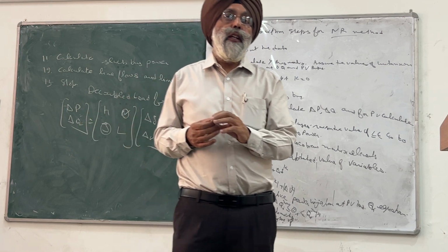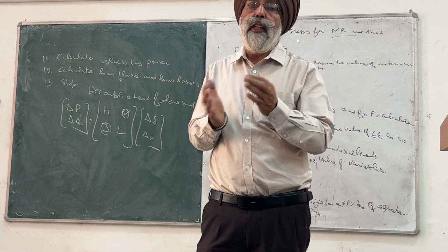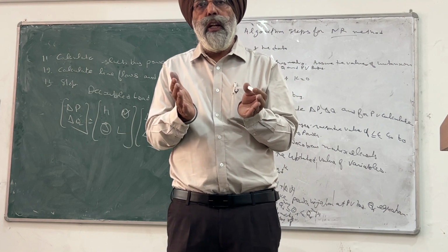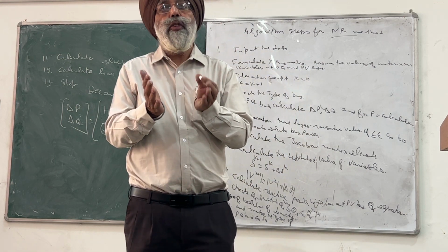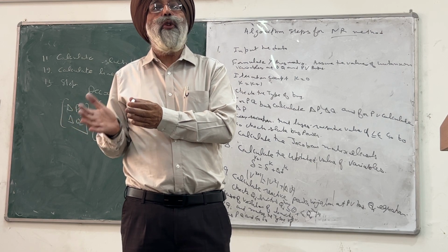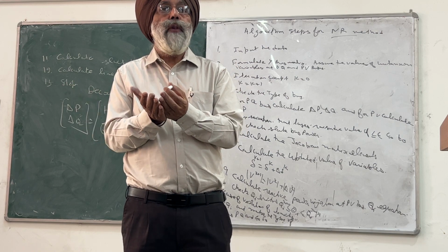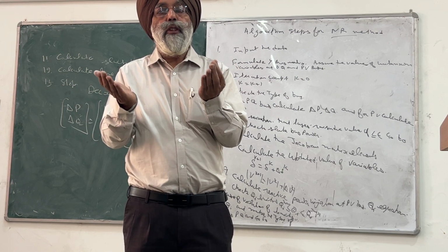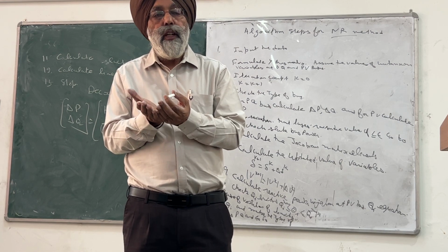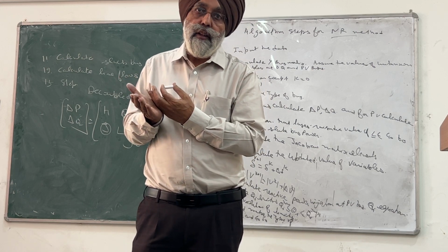But in the case of an interconnected system, a large number of machines are interconnected with each other. So all the machines must maintain the same quality level of the power. Same quality level of the power means the voltage level. When we are connecting the machines in parallel, the voltage of the machines must be the same, their phase sequence must be the same, and their frequency must be the same. So it must be maintained.